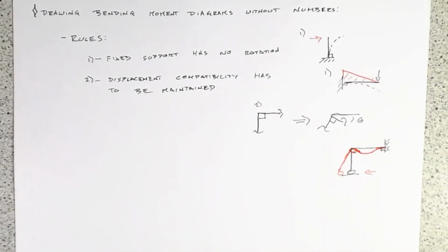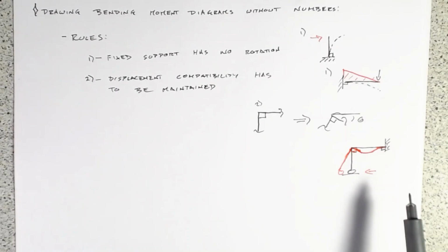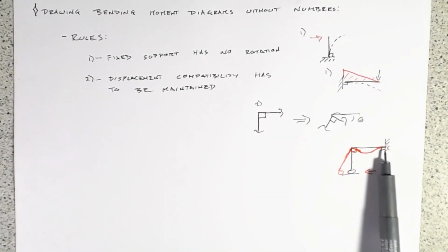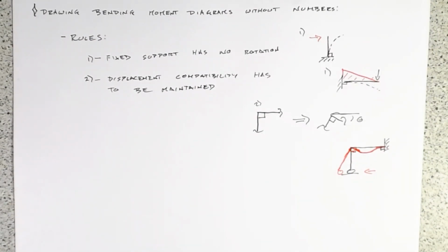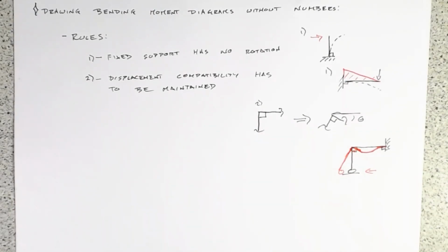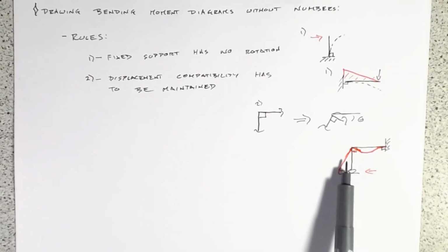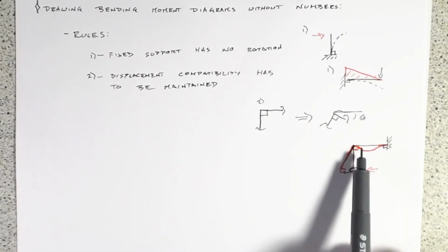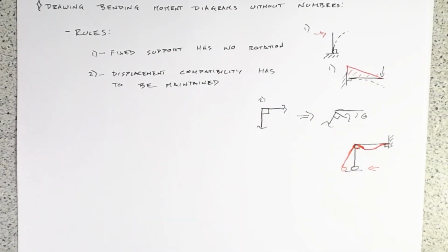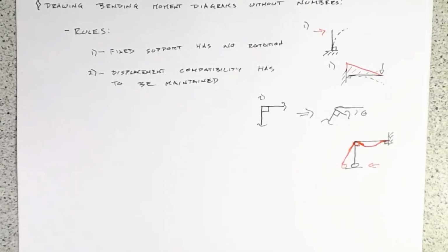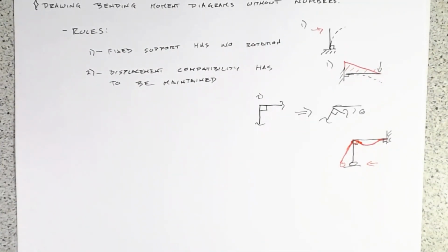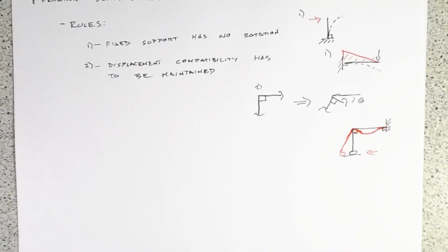So you can see how these rules can get applied, just relatively simple rules. Fixed supports, you can't rotate them. And if you have a joint or a corner which is fixed, or at 90 degrees, that has to stay at 90 degrees as you rotate that through. And then the only other thing which can move are the flexible parts of the beams in the middle. So that's our second rule. So now, our first 2 rules are really around displacements.